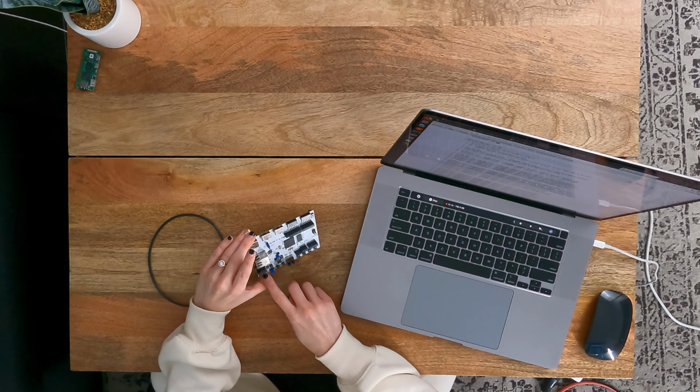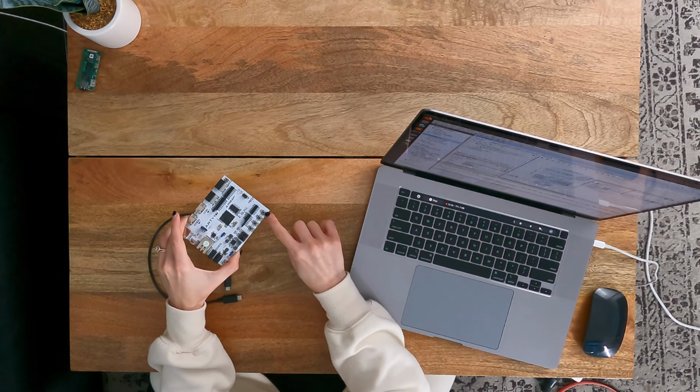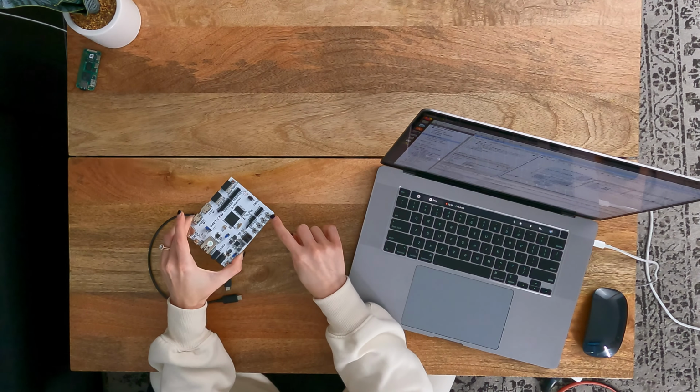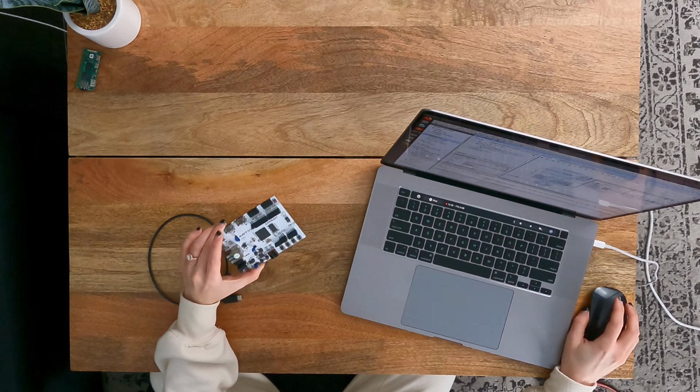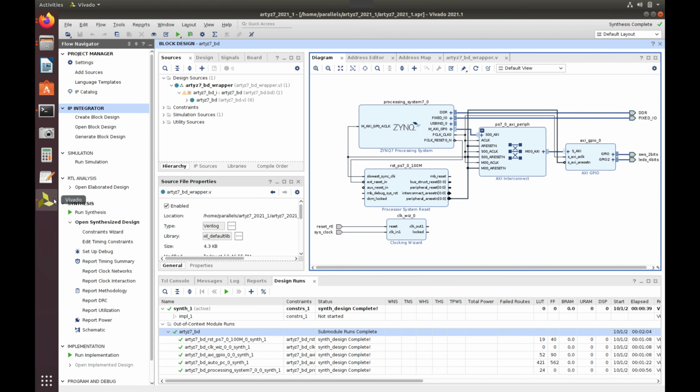So it looks like I'm just going to go ahead and connect. It looks like this software reset is just connected to the general reset. It's not connected to any of our package pins available to us. So let's see if we can use one of these other buttons. I left these four buttons unconnected here. I'm currently not utilizing them, so I think I'll just go ahead and use button 0 as my reset line.